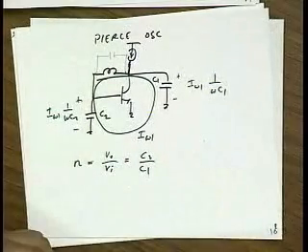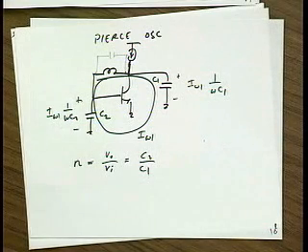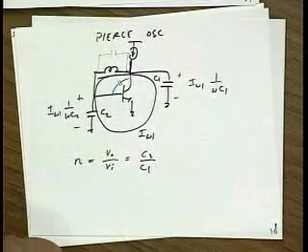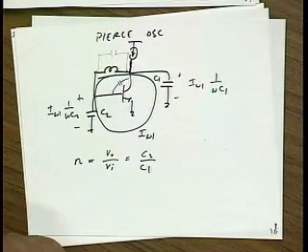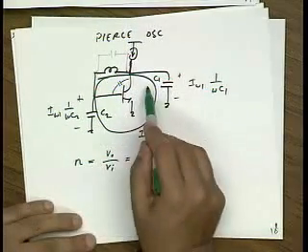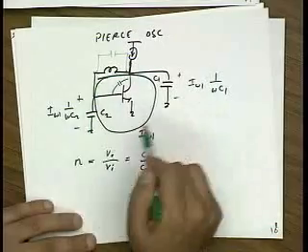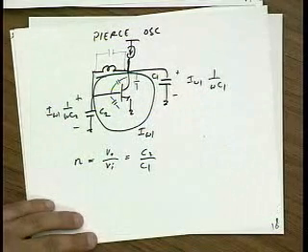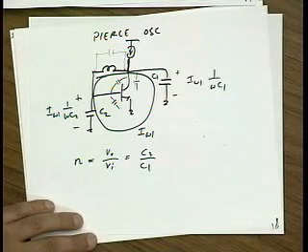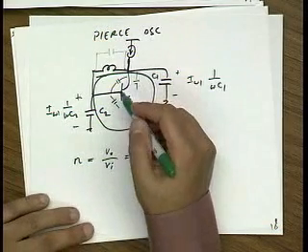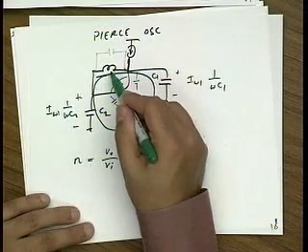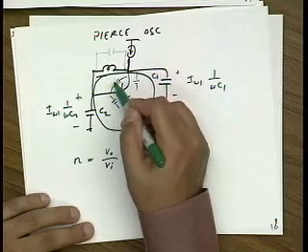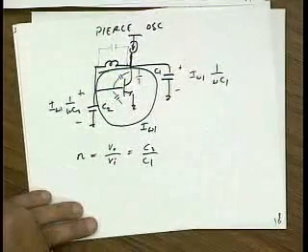Okay? Question? The C1 and C2 have to be large enough to swamp the Miller cap across the base-emitter. Yeah, that's a good point. So you have some Miller cap. C1 and C2 actually, because they're forming the tank, need to be large enough to pretty much dominate over all the parasitic capacitances in the device. The effect of the Miller cap is not so bad, because what it does is you can think of this cap in parallel with this inductance, right? So if the inductance dominates, basically this cap just changes the value of the inductor a little bit. You see what I mean?